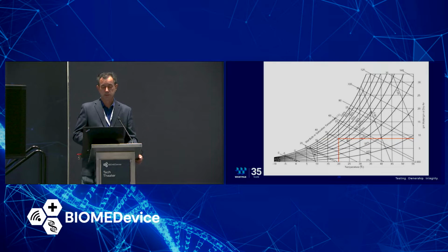And if we draw a straight line across, you can see that as temperature increases, the relative humidity starts to drop. So we started at 60, we cross the 50 and the 40 and the 30, and somewhere around 35 C, we cross 40 C, we cross about 20%. And by the time we get out to 55 degrees C, we're well below 10%.